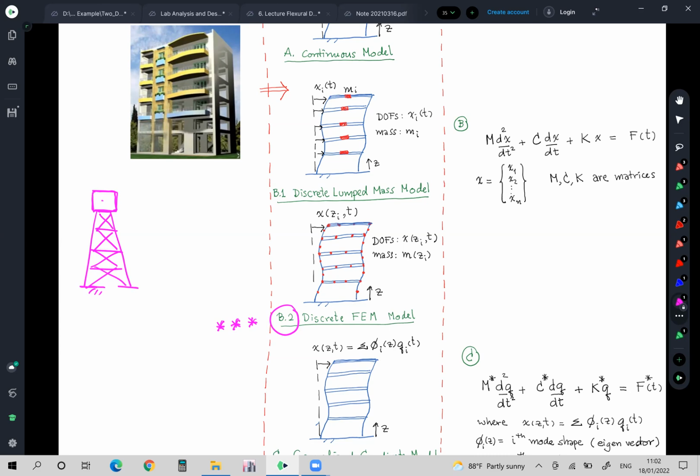If I use a finite element model, of course, I can test by changing the stiffness, by making the column larger or smaller. I reduce the mass of my building to be lighter or heavier. I change the damping of my building by adding a damper here or there in my computer model, and see the result and compare. It's possible. It takes so much time, believe me.